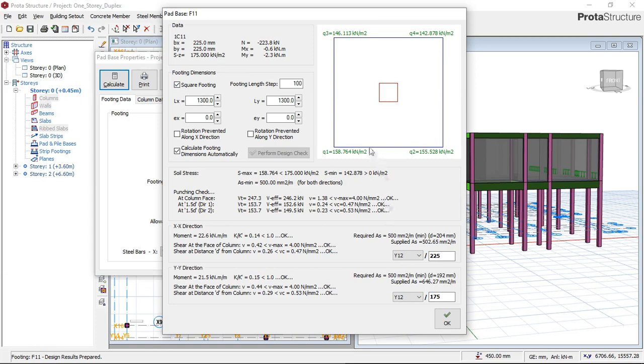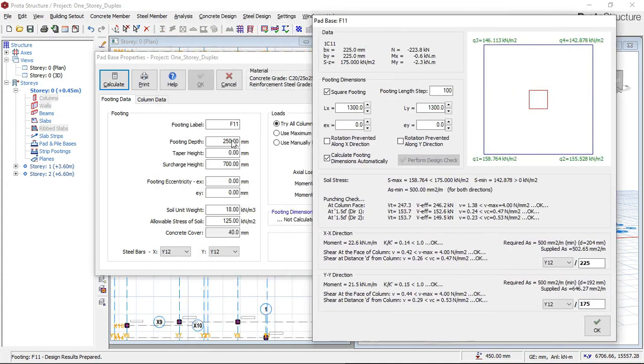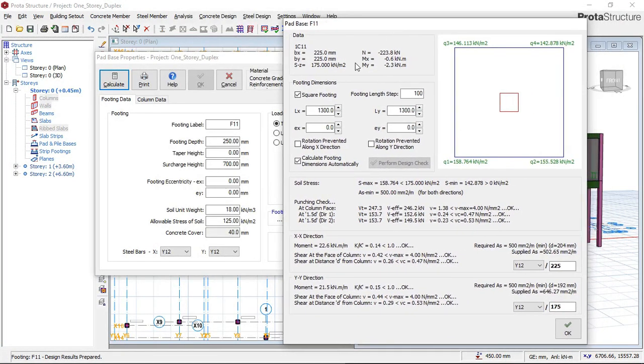Listen very attentively. Don't say that you're rushing on this area or your client is on your neck to issue this work. No, you must check this area. Once this place is not okay, I will advise you to go and increase your depth of footing. And if there is a level at which you increase your depth of footing and you're still having failure, I will advise you to change the foundation from footing to a wide strip foundation or a raft foundation. And I will tell you about that in our recent videos.